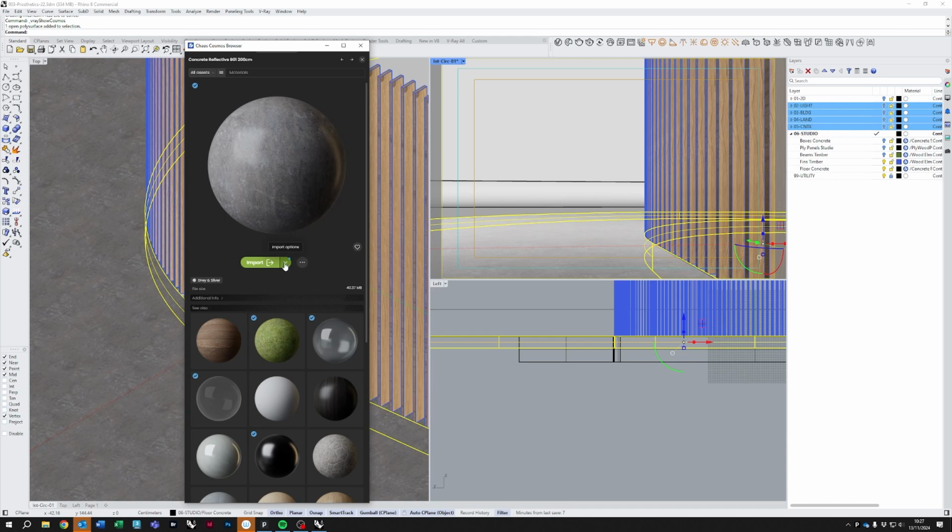So on import, you notice this little option here that you have, and you can enable triplanar mapping. Basically, triplanar mapping will create its own mapping on all objects that you create under this material, and it will mean that the overall scale of this map and the orientation is fixed. So this really only works for material like this, or the grass, or perhaps a mesh that always runs in a certain way, or cloth that is a sort of infinite material and the orientation does not matter.